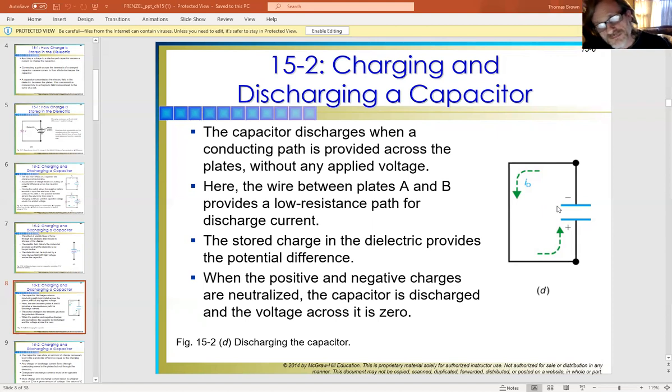So whenever I started to work on one, just to be sure, I'd take this big resistor from my toolkit and just slap the wire leads across that thing. You could do it with a piece of wire, but the piece of wire would take that instantaneous charge, and it could be a little destructive. But if you use a really large ceramic resistor that can handle a lot of power, you can use that to discharge the voltage out of the capacitor.